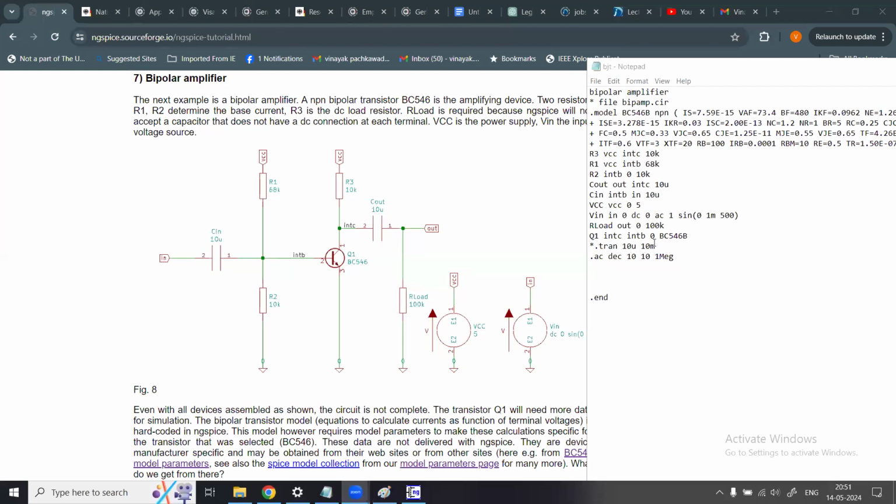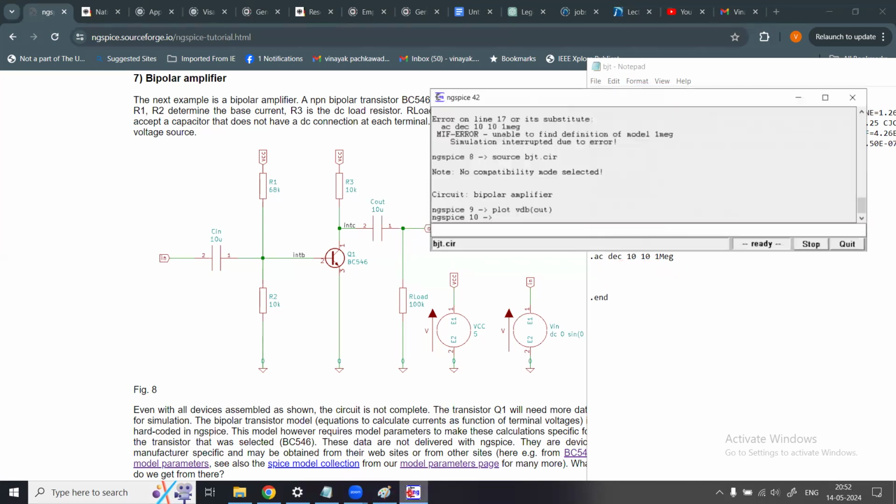Okay, so what I'm going to show you now is the result of this AC analysis. We are running this AC analysis, and we'll see how the output looks. We basically have to plot the output magnitude with respect to frequency, and the phase of the output with respect to frequency, and AC analysis will let us do that.